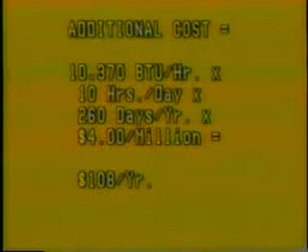Shall we reheat the air? No. Let's look at this calculation to prove my point. The additional cost of reheating the air equals 10,370 BTUs per hour times 10 hours per day times 260 days per year times $4 per million BTUs, which equals $108 a year, based on occupied time periods.